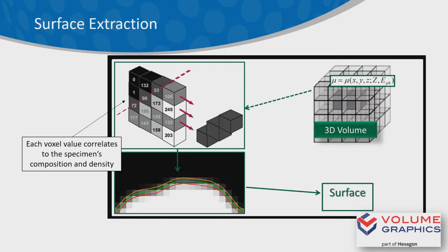And then what we can actually do is use those transitions to build a surface. And this can be a very, very precise method as well. There's a lot of work and ways to calibrate data. So in a lot of senses, there are a lot of people using X-ray tomography as a metrology tool. So we can understand its uncertainty, we can understand its limitations, and again, put it in the toolbox with all these other surface capture, geometry capturing tools. And again, that makes it very powerful. And there's a lot of different software packages out there to do that. One example we had here was the Volumetric software that we use, which takes this voxelized three-dimensional data and allows us to do all these complex measurements on it.